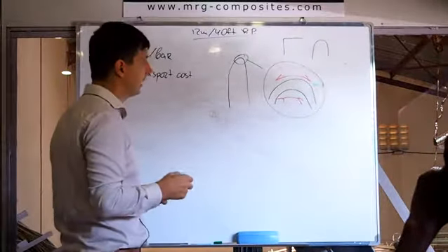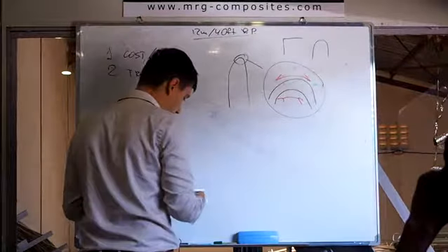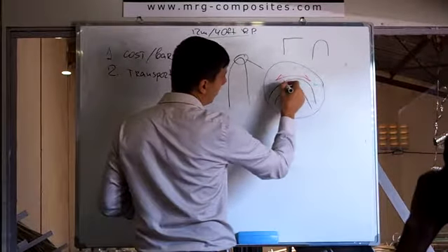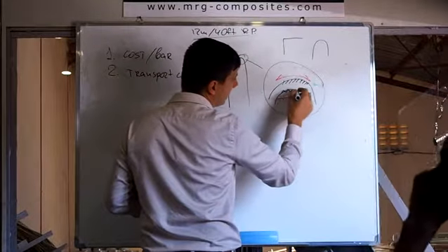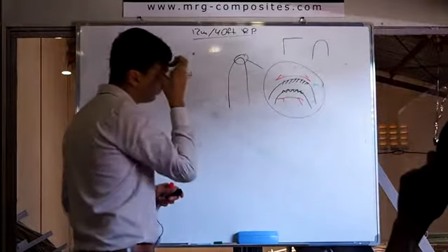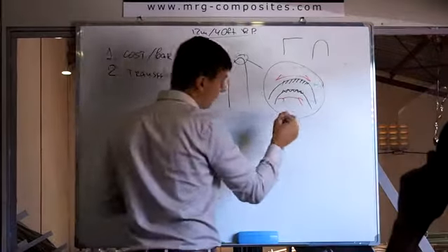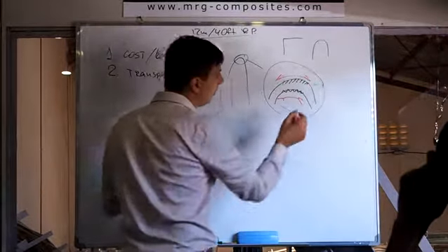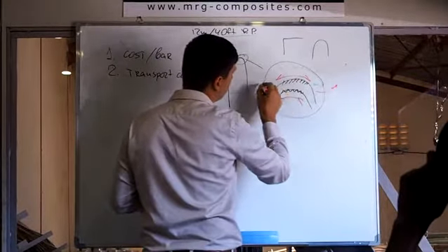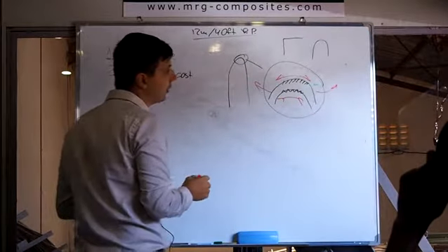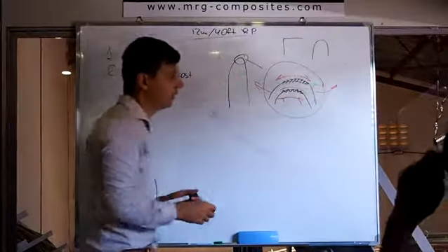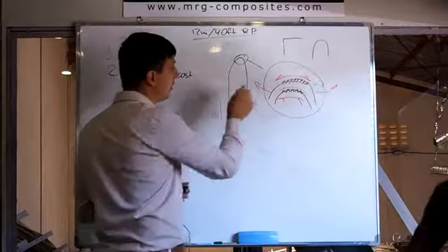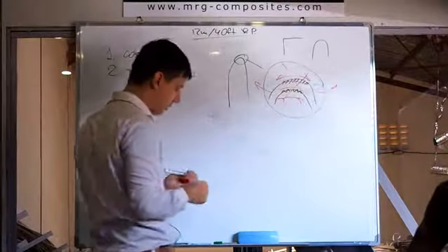The problem is that once you bend it, here we have, let's say, stretching of material, here some compression of material. Once you unbend it back, you're going to get weakness here and weakness here. So this we're going to call stress point.